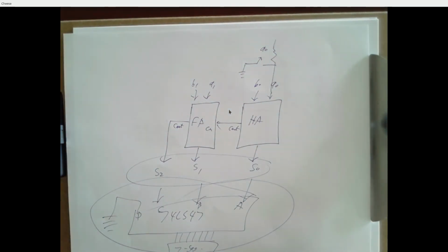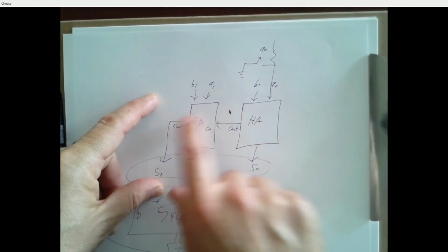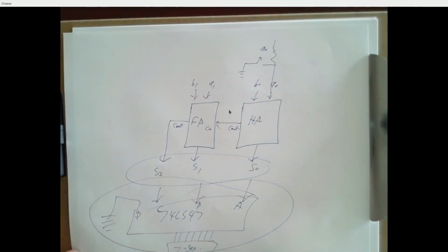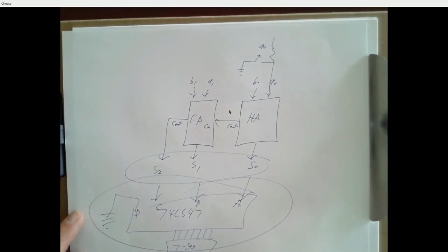Yeah, I don't know if I missed something, but is that adder a chip, or do we have to use AND gates and OR gates? So you're going to use AND gates and OR gates to make a half adder and a full adder and put them together to make a 2-bit adder. Cool. Yeah, so write down the truth tables, equations, minimize, wiring diagram.